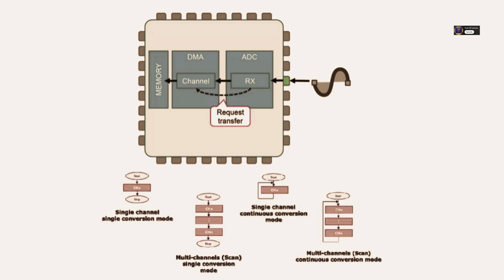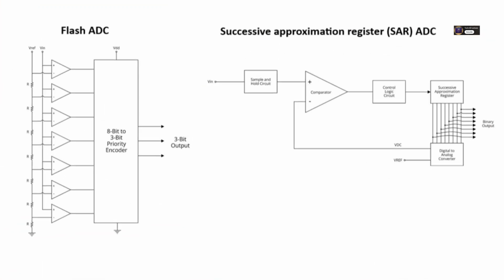We'll definitely want to circle back to DMA later, but before that, what's fascinating here is that you mentioned different architectures. So there isn't just one internal blueprint for an ADC. Not at all. They have very different internal personalities, we could say, optimized for different things. Like what? Well, take flash ADCs, also called direct conversion ADCs. These are the speed demons. They use a massive bank of comparators, one for almost every possible output level, essentially checking all possibilities in parallel. Incredibly fast. What's the catch?